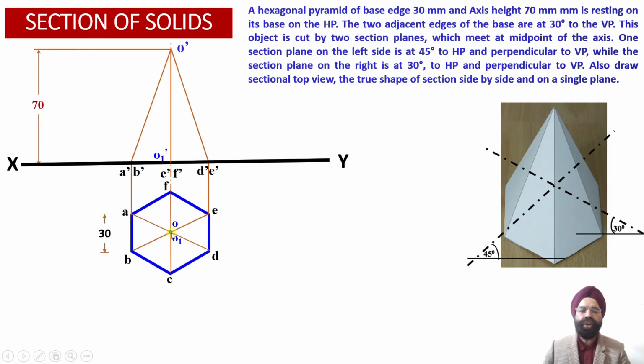Similarly, over here also the slant edge OE lies on the rear side, and the slant edge OD lies on the front side. Now this slant edge OD is going to cover the rear slant edge OE over here. So in the front view projections, we obtain the object line projections corresponding to O dash D dash, superimposing the hidden line projections corresponding to the slant edge O dash E dash over here.